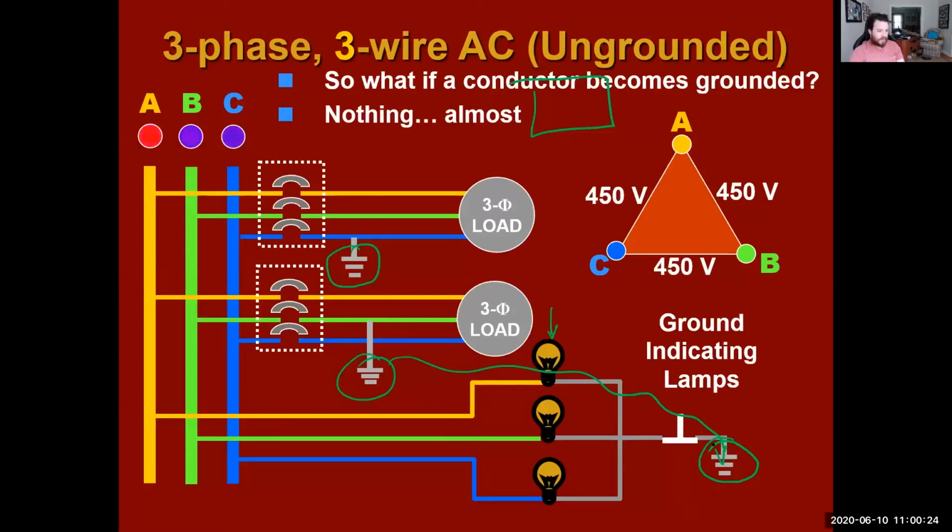So we can't follow this. The problem is you're not going to be able to follow all of the runs of all the cables. In order to find your ground, you have to start at a larger area and break it down so you can get a smaller area, or maybe one stateroom. It might be in the second engineer's stateroom.